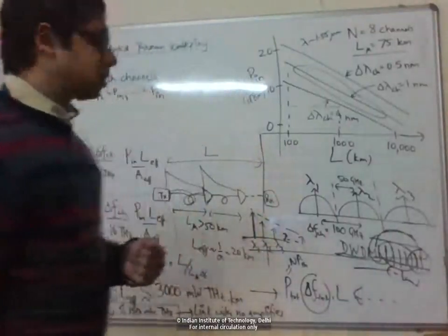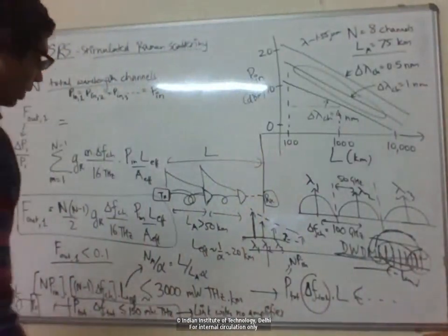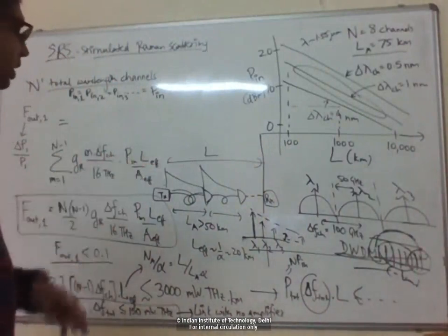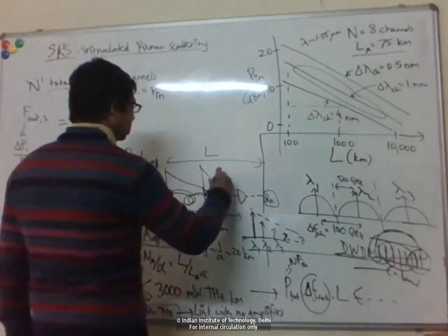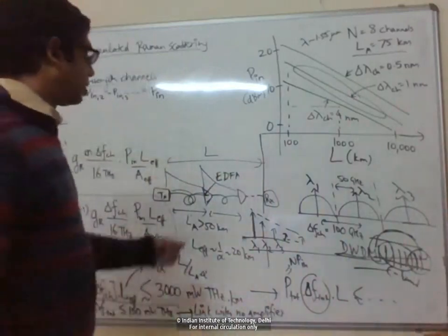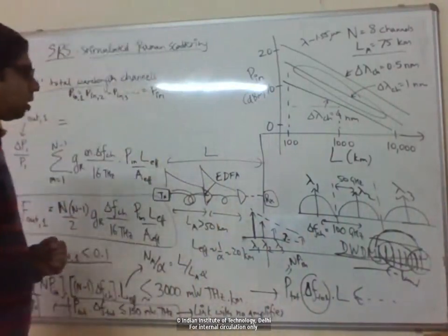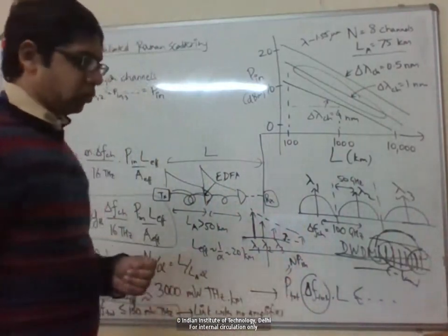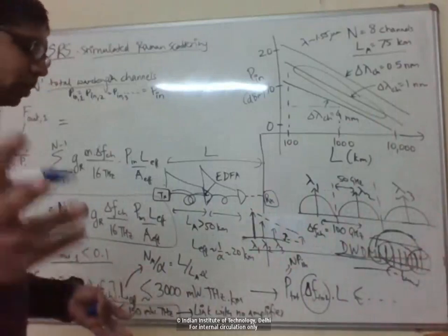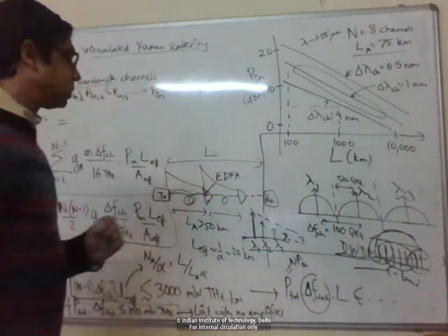There are also Raman amplifiers. So again, this Raman effect can also be used for something useful, and one place where it is used in optical communication links is for these amplifiers. Of course, EDFA is the standard amplifier which is used. It works for the C band and also for the L band, but it doesn't work beyond. So if you want to go to other bands like the S band or U band, then you have to use some other types of amplifiers.